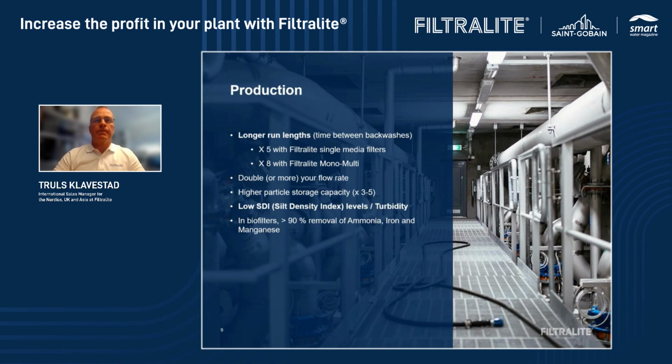We have also seen that you can increase the flow rate. Very often you can double the flow rate or more. The limitation when you increase the flow rate is the water quality. Because all of us working in the water business know that with higher speed there is a higher possibility that the suspended solids will go through the filter.